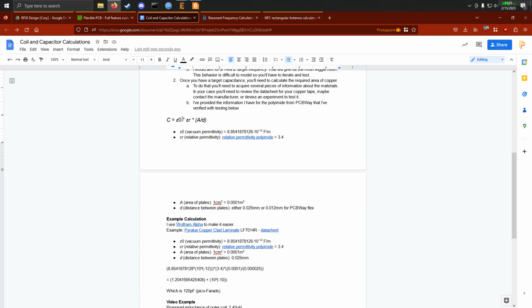So there's a permittivity, which is the capability of a medium, like air or something like that, to support the propagation of electric fields. Because what we're doing here is we're putting a metal plate and then a separator, which is a dielectric material, and then another metal plate. So that permittivity of that separator is how difficult or easy it is for the electric fields to propagate through it, and for the material itself to be charged positively and negatively on one side versus the other.